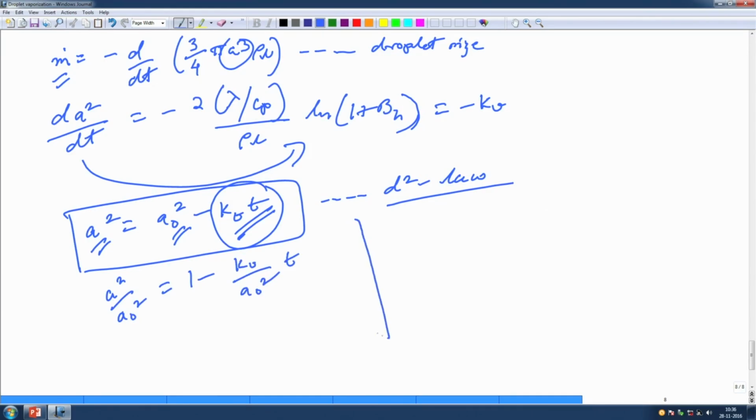So, this will show a decay characteristic like this. It will start when A naught is the same as A1, so the time axis will start from there, and you can see it is a gradual reduction of the slope, which is expected, because A decreases with time. So, this is basically the d square law that we have derived out of this entire exercise.